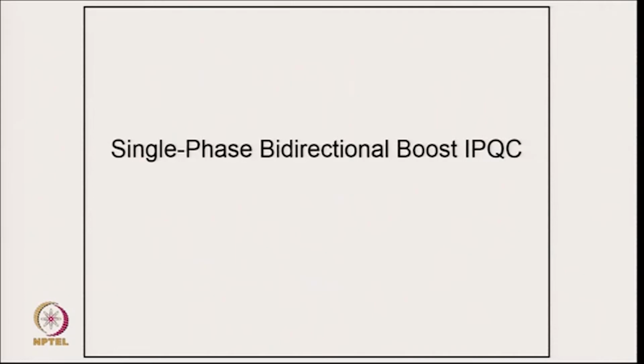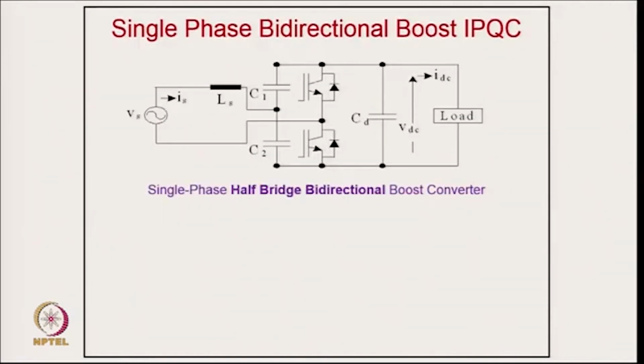So these were the unidirectional converters of 2 kinds; we gave an example as well as the design concept. We will consider some more examples later. Now, coming to the single phase bidirectional boost converter. This is typically the first boost converter circuit, with 2 devices and 2 midpoint capacitors at the output. What is the benefit of it? You can have bidirectional power flow. You can feed the power from this side to this side or this side to this side. But the disadvantage is that the entire current has to flow through this capacitor, so the size of the capacitor will be large also.